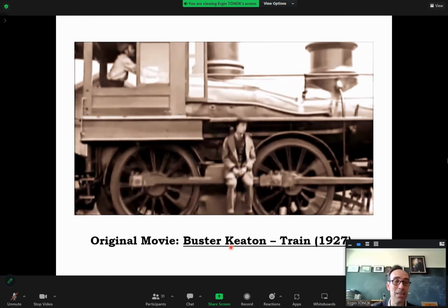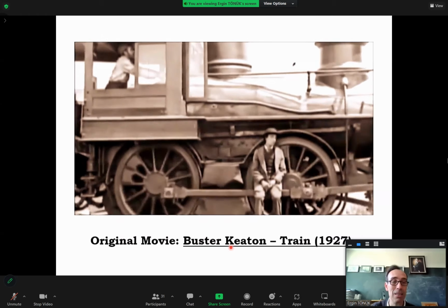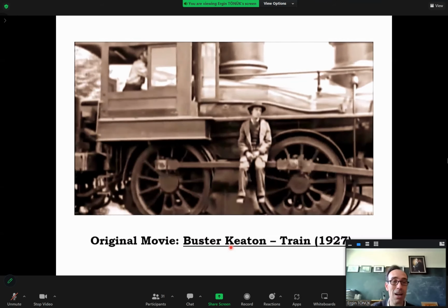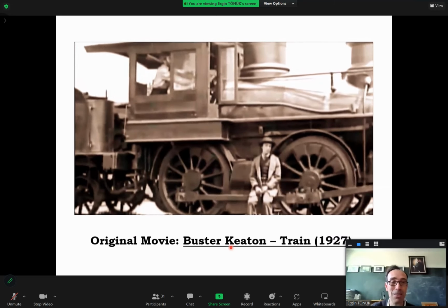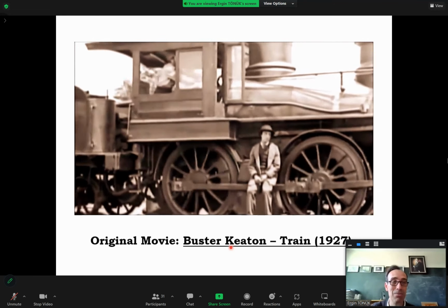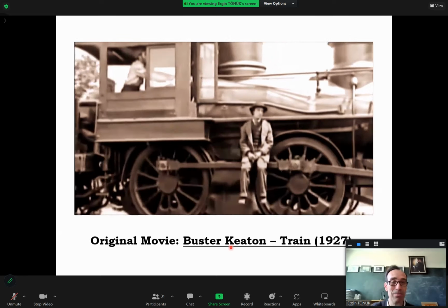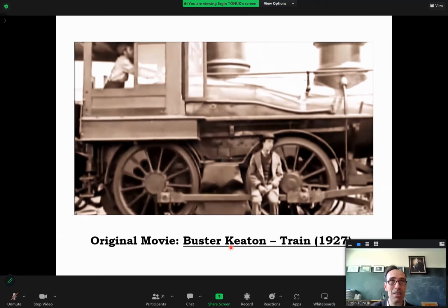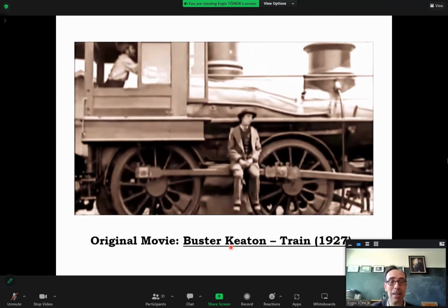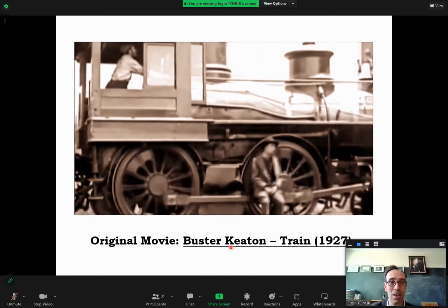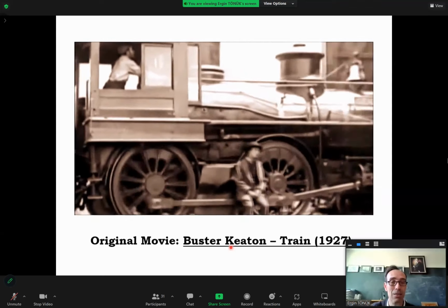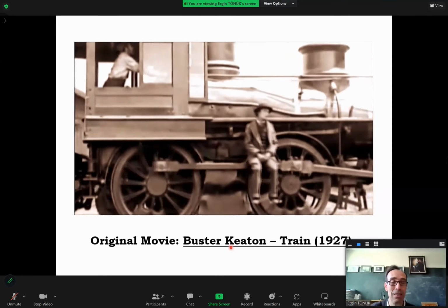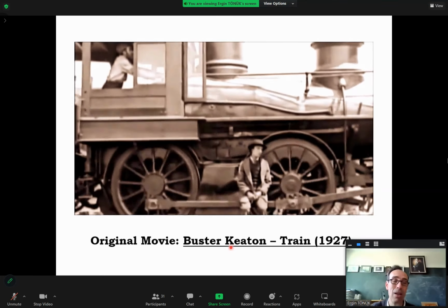As you see, the connecting rod is always parallel to the ground, and the man could sit on it, although it's quite dangerous. So it's in translation, okay? Its angular position does not change. Therefore, it does not have an angular velocity nor acceleration.